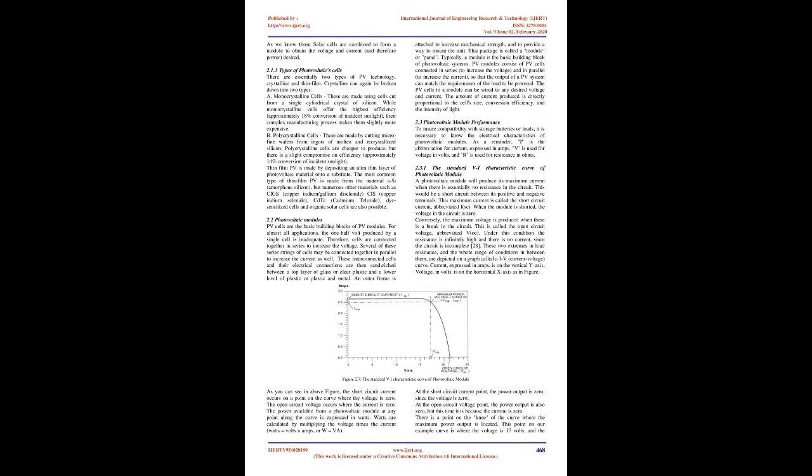Eduardo Roman, Ricardo Alonso and Pedro Ibanez [14] presented a paper about the intelligent PV module concept, a low-cost high-efficiency DC converter with maximum power point tracking, MPPT, functions control and power line communications, PLC. In addition, they analyzed the alternatives for the architecture of grid-connected PV systems: centralized, string, and modular topologies. The proposed system, i.e., the intelligent PV module, fits within this last group. Its principles of operation, as well as the topology of the boost DC converter, are analyzed. Besides, a comparison of MPPT methods is performed, which shows the best results for the incremental conductance method.